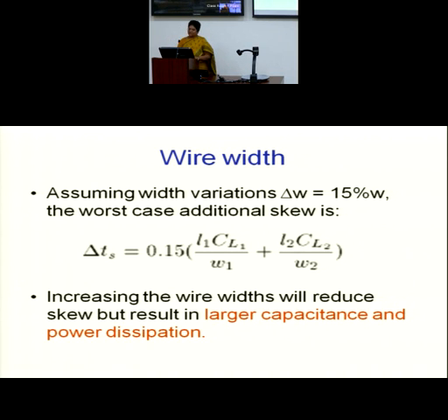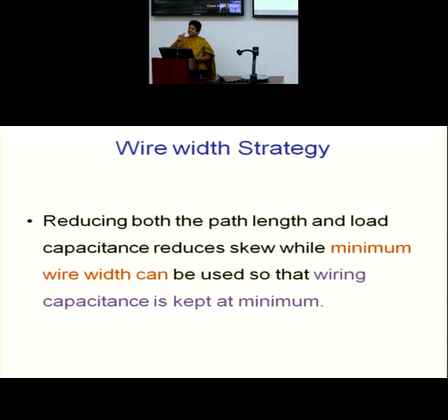Now next we come to the segment length. Segment length, as I said, is determined by buffer insertion points. If you are following the equal path length approach, L gets automatically set following that algorithm. So how many buffer insertion points do I need? Where to stop? As I said, the guiding parameter is skew.